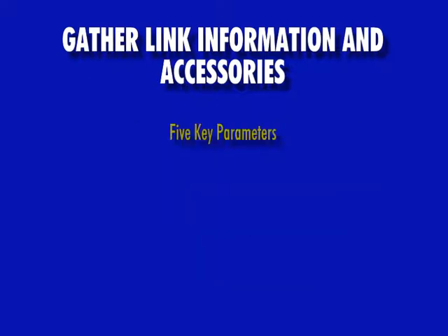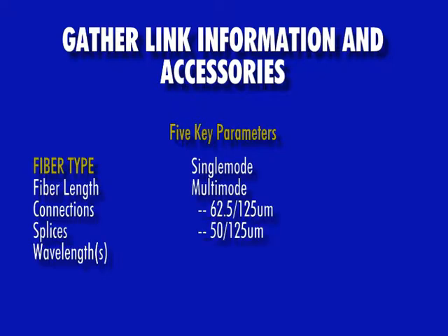There are 5 key parameters that apply to any fiber optic test. First is the fiber type, which will be either single mode or multimode. In the case of multimode, this could be either 62.5 or 50 micron.